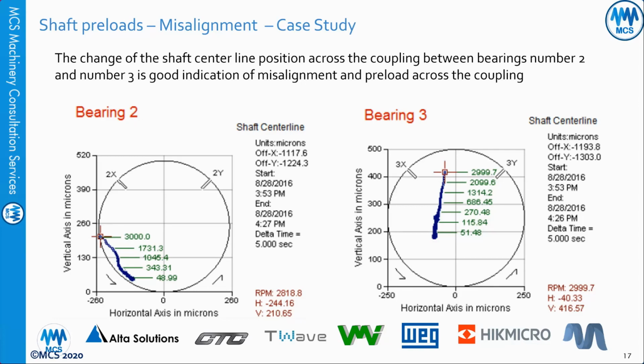And you have from one side the shaft weight, the gravity, and the internal forces of the shaft, and you have the pressure of the oil wedge from the opposite side, plus some tangential force and some other radial forces, and this will put the shaft in an equilibrium position. This is more in rotor dynamics. But come back to the shaft preloads.